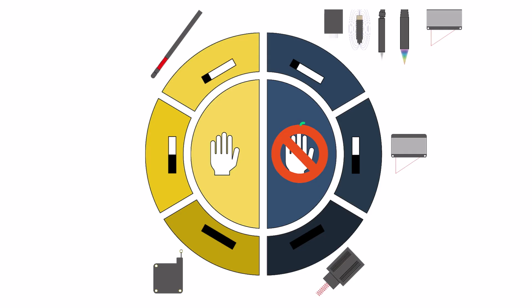And in the last example, we want to measure the distance to a silicon wafer on an air bearing. Here we again need a non-contact system, and since we might want a bit of standoff from the expensive wafer, we should go with an optical solution. For such a specular target as a wafer, the confocal and interferometer technologies are ideal, so now it really depends on what accuracy is needed.